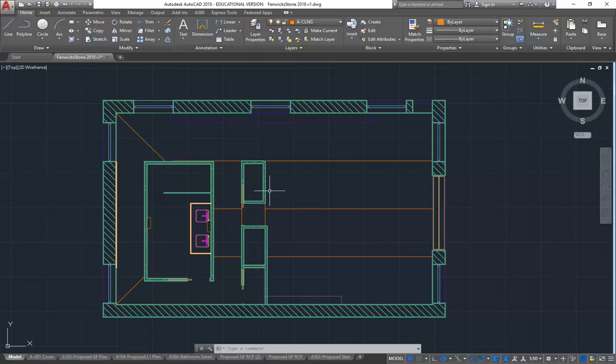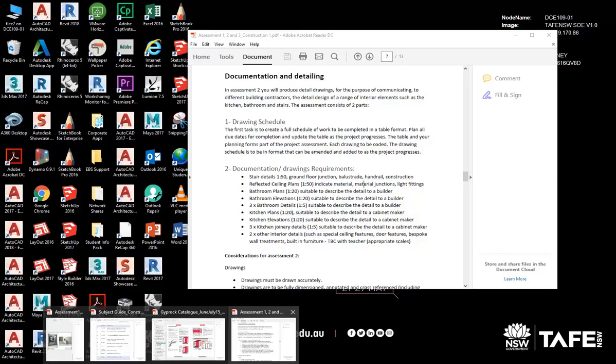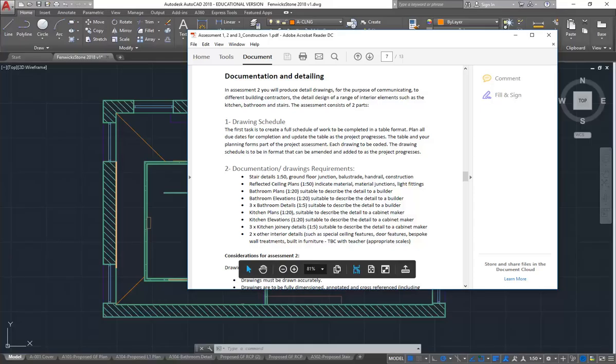And these can be placed on the sheets, just the same as any of the other views, of course. So that's the basic idea with reflected ceiling plans. They're, in this case, mainly to show lighting, but also your emergency services. And so there, you do need to indicate material, so it should, in most cases, be plasterboard, unless you have an exposed floor or ceiling structure, in which case you just note that.